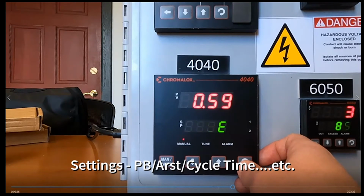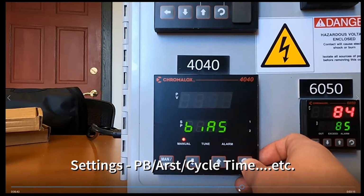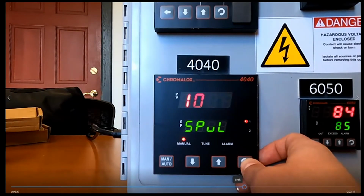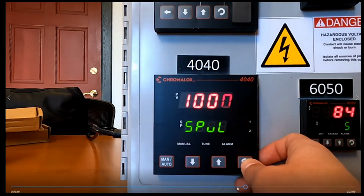Yep, absolutely. And then the rate here is the derivative time, or the D in the PID. Sort of a similar thing, but you're actually looking at the slope, or into the future, if you will. Not to get all math on y'all, but if you take a derivative of a function, you're getting the slope, and that's basically the controller trying to calculate where you're going based off of that. So if you want to pause real quick, actually, Derek.